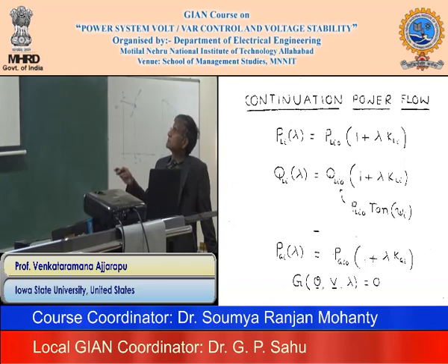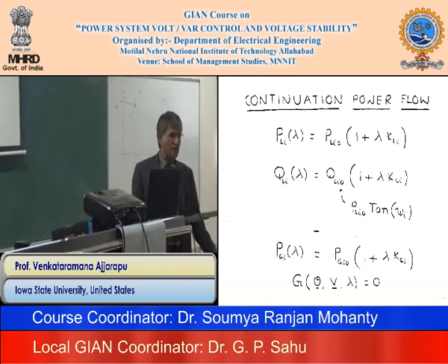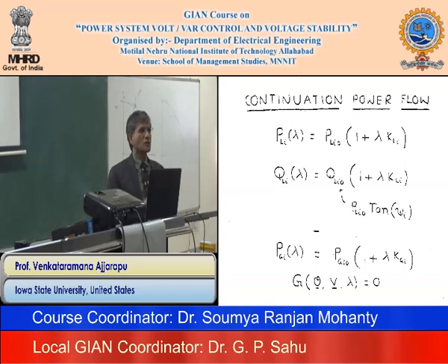Okay, so once you have that, these are the equations of real and reactive powers. That's a function of theta, V and lambda also, right? Of course, lambda is an independent parameter. Remember here, lambda is independent of P and Q. That's why I call lambda a connected load. Connected load means this PLi0 depends on V, though in this case we are assuming constant power.